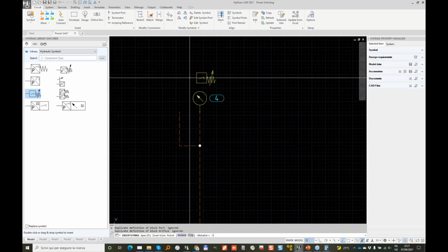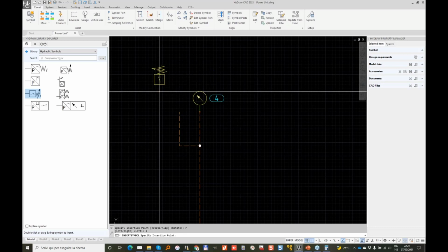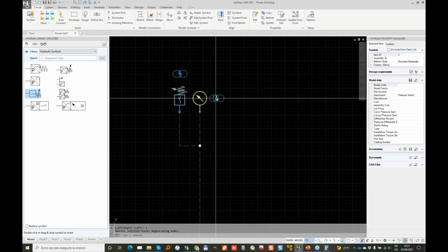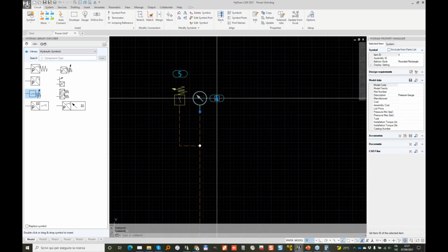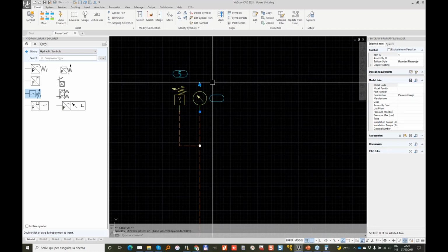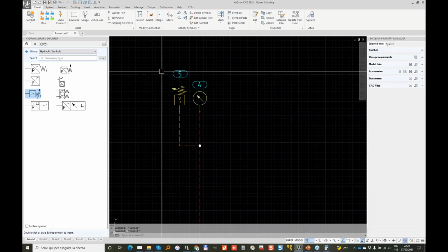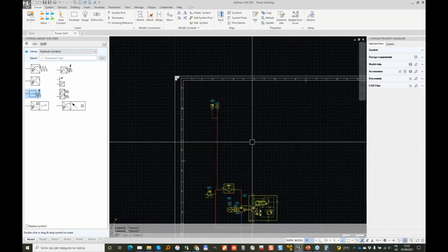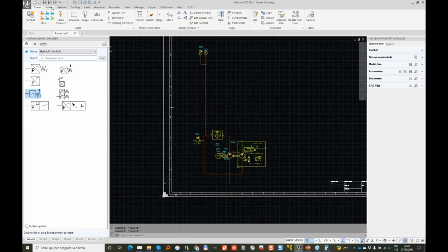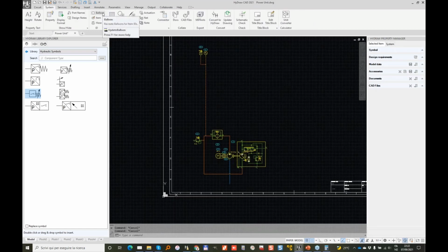And this is, I'm going to rotate left and place on top of the connection line. You can move the item ID. Now, in this case, the balloon is not following. If this is not happening, there is a quick way to restore the balloon just by selecting and changing the balloon style, or we have a fast command to do that in one go directly in the System tab. It is called Balloon. I may use it later.